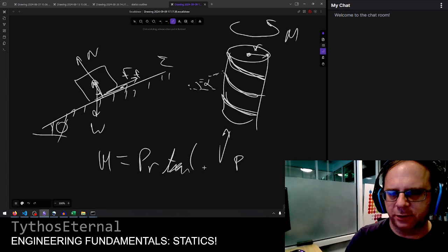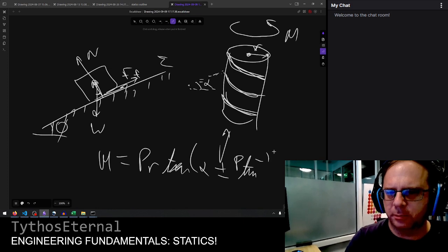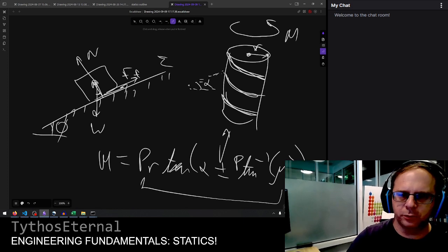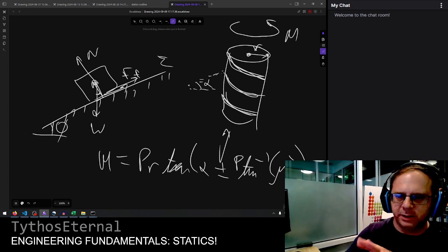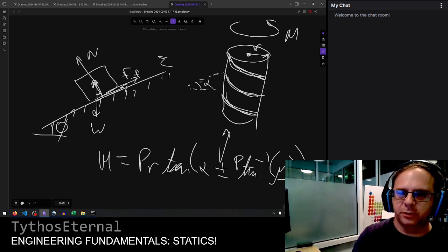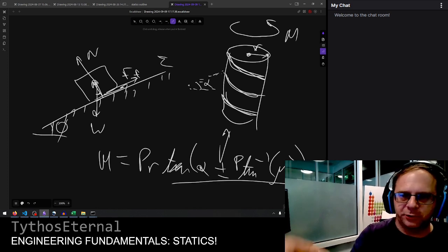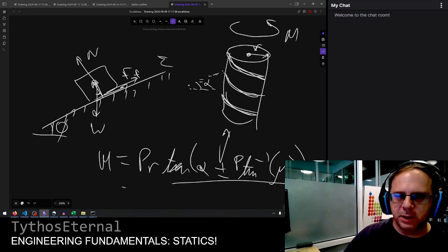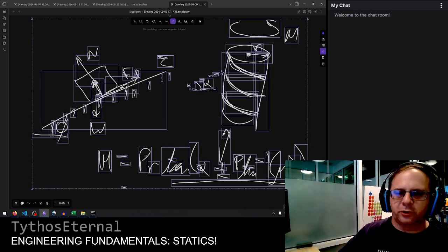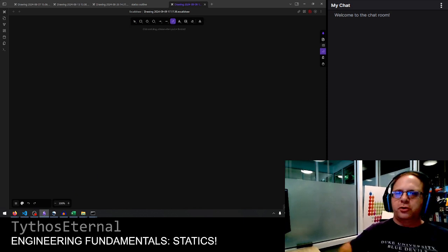And it's like an angle of angles situation where, depending on which direction it's going in, it's actually the frictional coefficient, right, product of the load, the normal, combined in an angular space, like depending on which direction, it's the inverse tangent of the frictional coefficient with that pitch angle that you use to model the resistance of the screw and the moment it's applying through the material contact to bear that load P. So there's fun ways to combine these, of course. But we're not going to spend too much time on that.